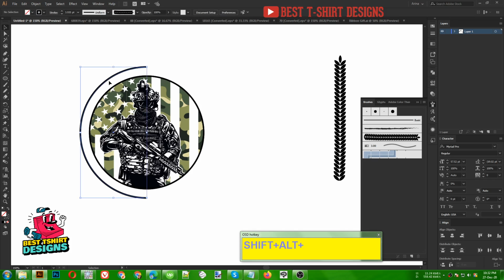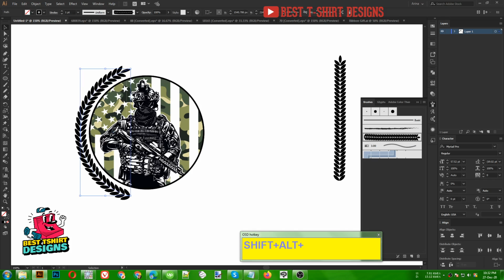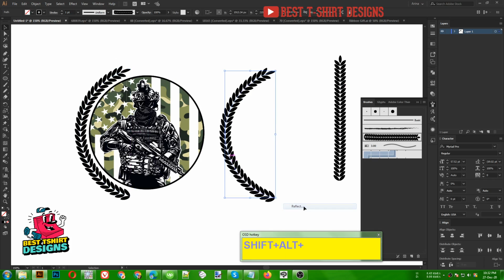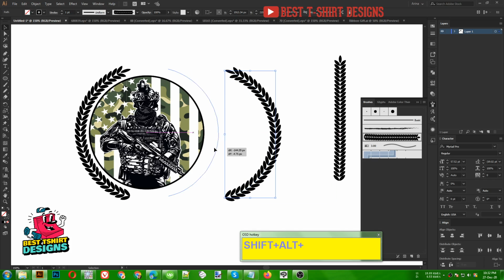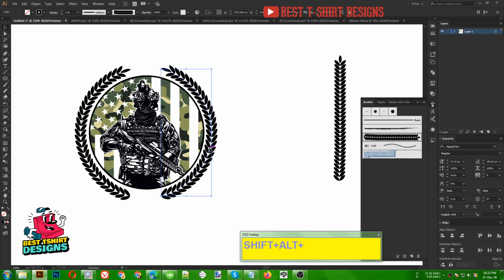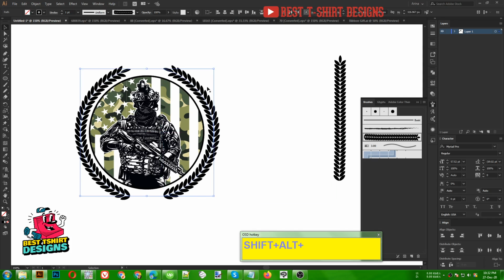Now for this one here, I don't want it to cover the total area, so if I press Shift E for eraser tool, I can erase some part of the ellipse, something like this. Yeah, that much is good. And now if I select this shape, I can click here. It is going to fill it with that shape, and that's why we created a longer shape. If I just created a pattern brush, it will fill the entire area. And you can try also with pattern brush, that is good, but I thought here the art brush will work great, something like this. Now of course not too close, something like this.